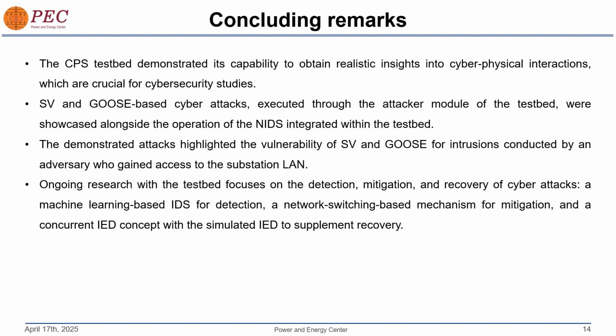In concluding remarks, the presented cyber-physical security testbed demonstrated its capability to obtain realistic insights into cyber-physical interactions, which is critical for cyber-security studies. And we have also presented SV and Goose-based cyber attacks executed through the attacker module alongside the operation of the network-based intrusion detection system. The demonstrated attacks highlighted the vulnerability of SV and Goose to intrusions conducted by an adversary who gained access to the substation local area network.